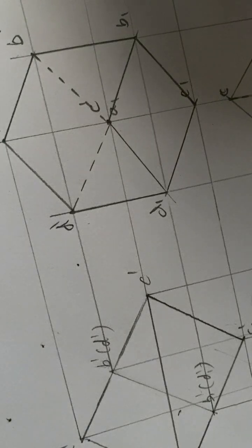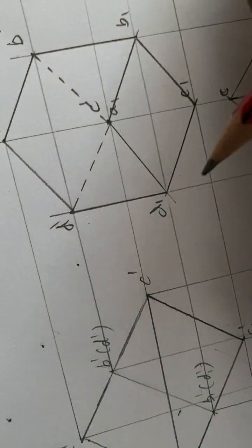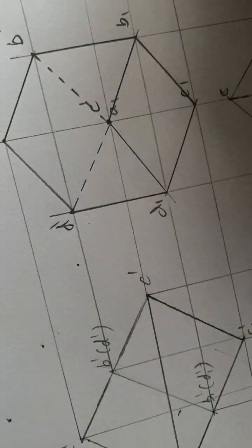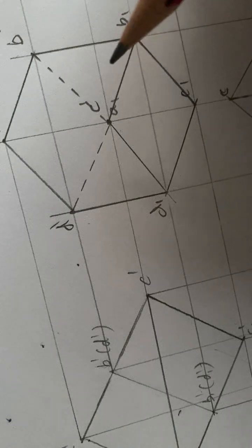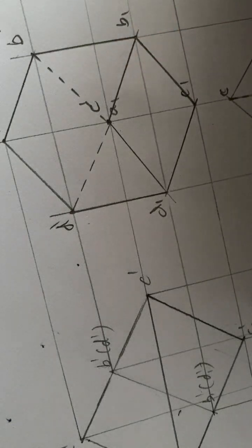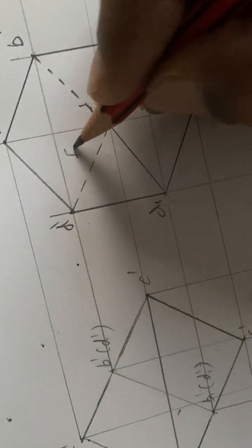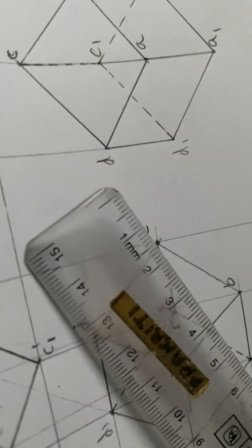Okay, so can you see the cube? This is visible, that A1, B1, C1, D1 is visible. Okay, and because you're seeing this as a front view, because it is tilted, right? Then you can see the edges A1, D1, B1, but you can't see B dash, C dash, and C dash, D dash. Okay, so that completes. This is your front view, this is your top view.